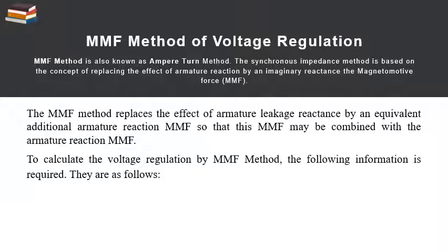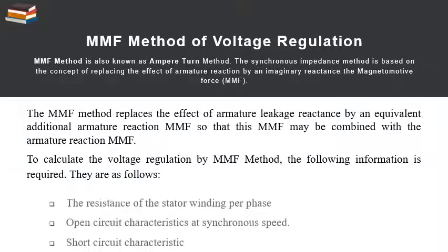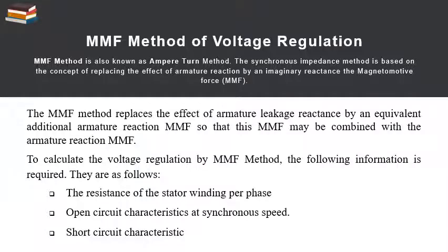To calculate the voltage regulation by the MMF method, the following information is required. They are as follows. Number 1, the resistance of the stator winding per phase. Number 2, open circuit characteristics at synchronous speed.